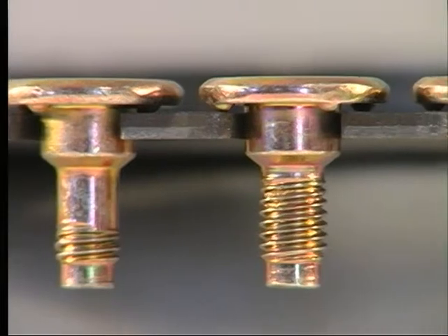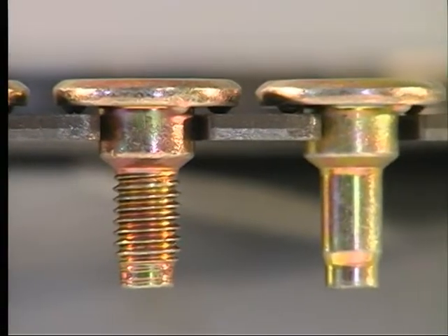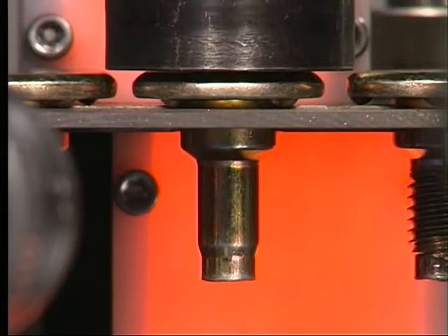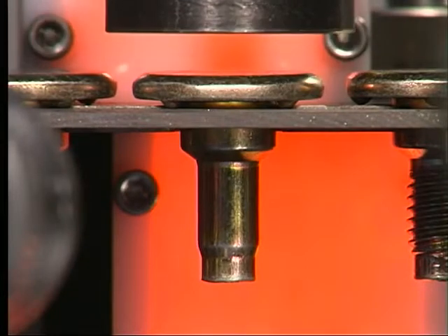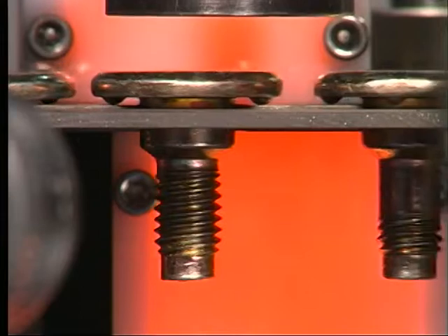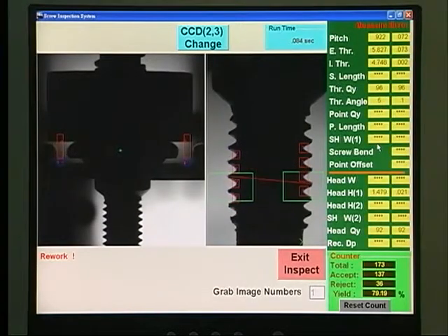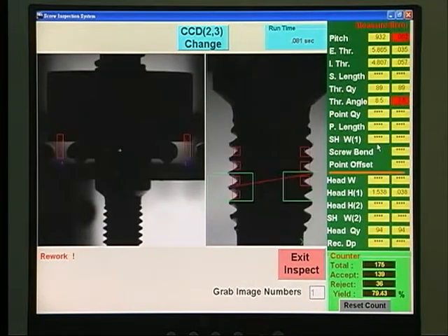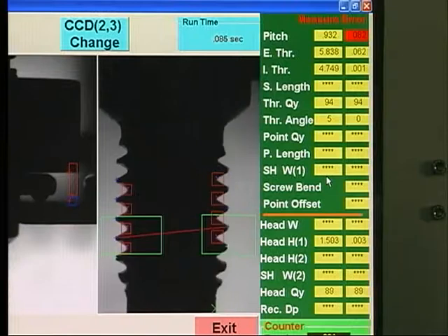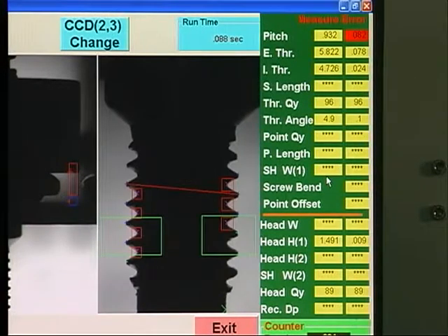This feature of the program screens out screws with problems like half thread, bevel thread, and no thread. The image of the screw thread is grabbed by the program and compared with a sample previously taught to the program. The passing level is determined by a required level of similarity. The evaluation of similarity is based on the theory of pattern matching, without further assistance from the camera.